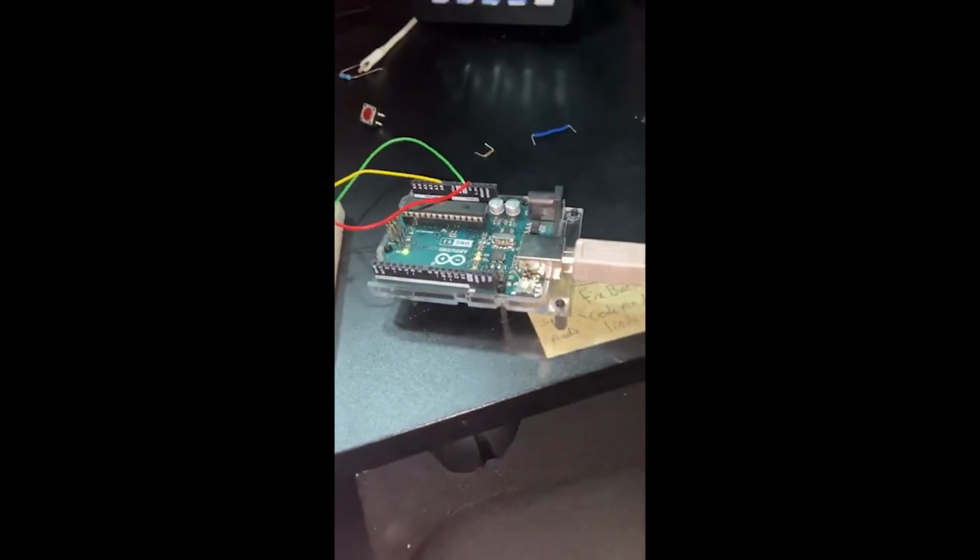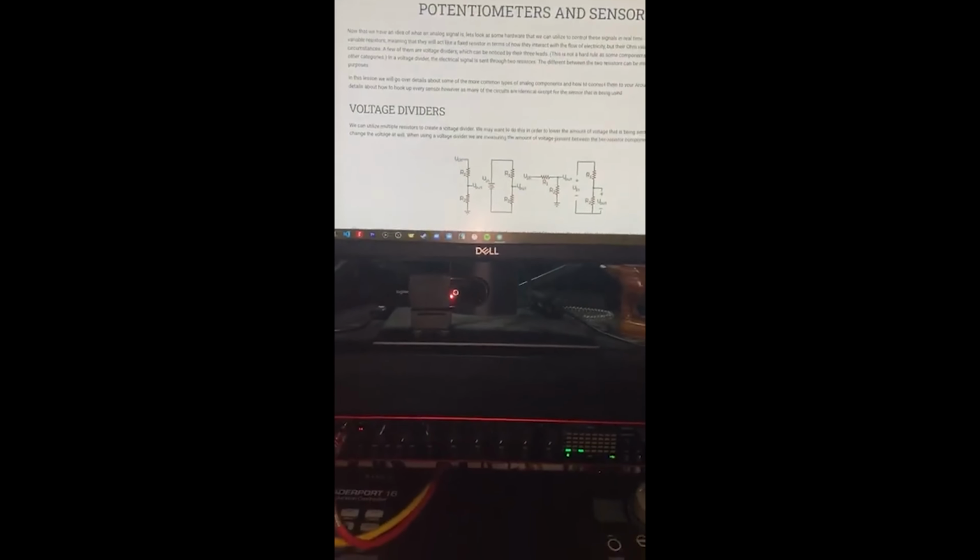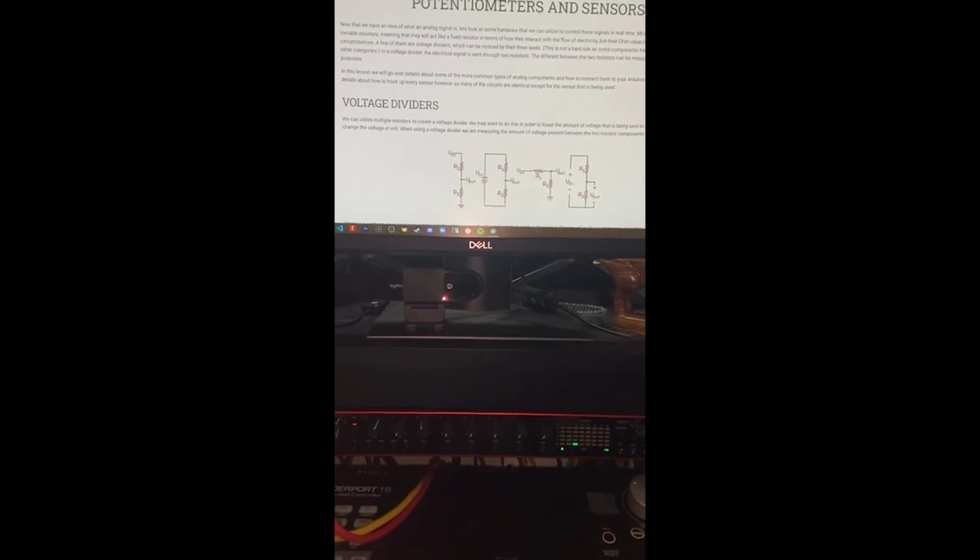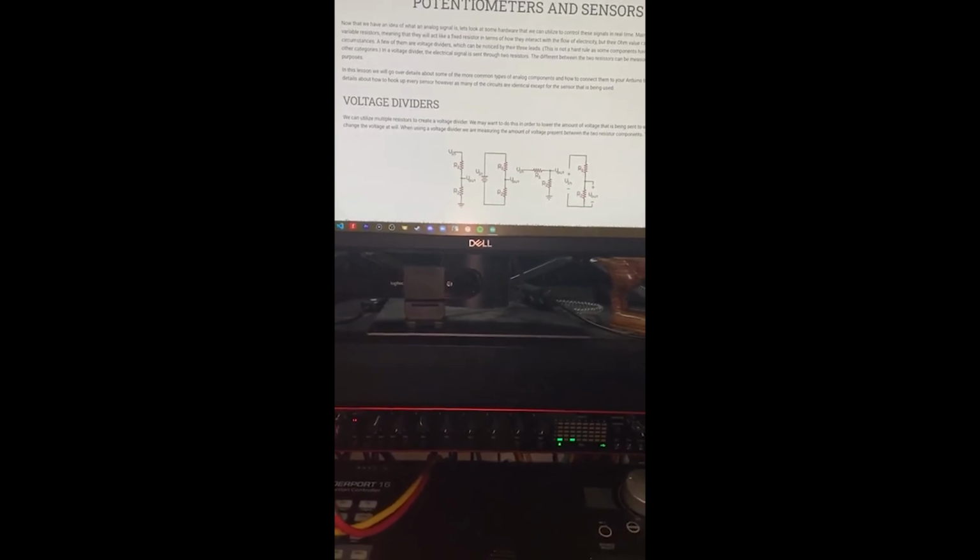So in order to be able to do anything with that, we have to take the voltage and divide it. And this is the core circuit-wise of what we will be doing here, is creating these voltage dividers. So basically the way the voltage divider works is that we have, I'll use this one and the second one here as the example, the flowing electricity. It's doing its thing just like normal. We have one resistor and a second resistor in the circuit, and then in between them we are measuring that output voltage of the circuit.